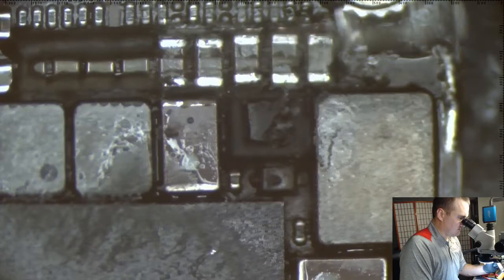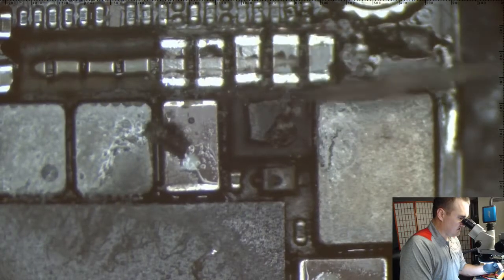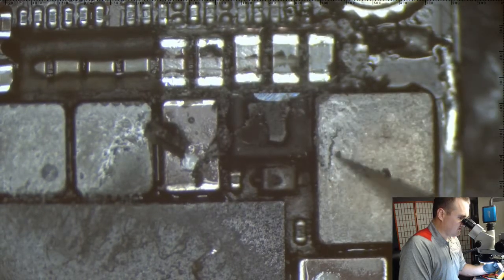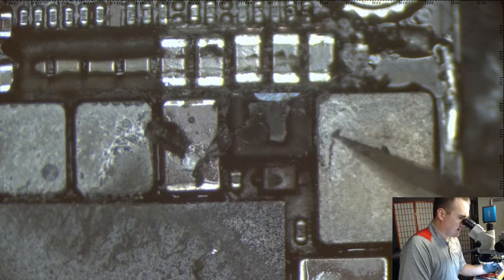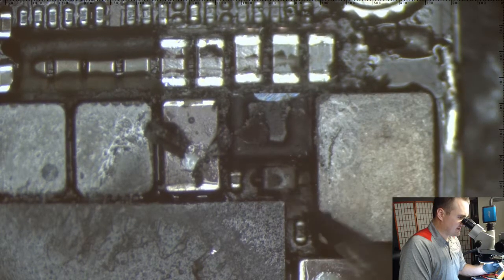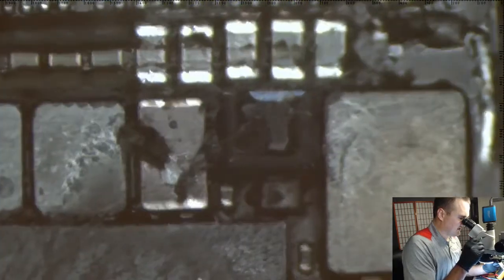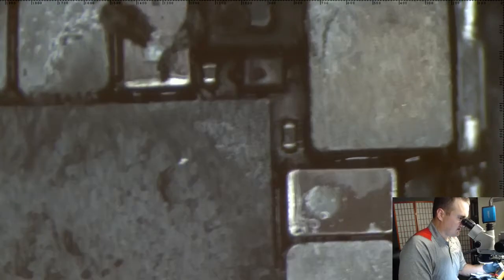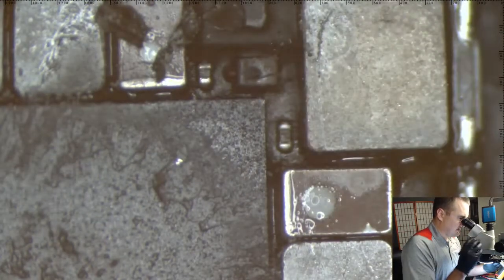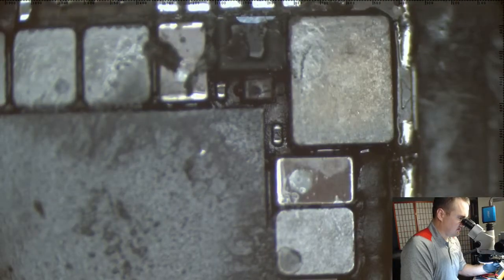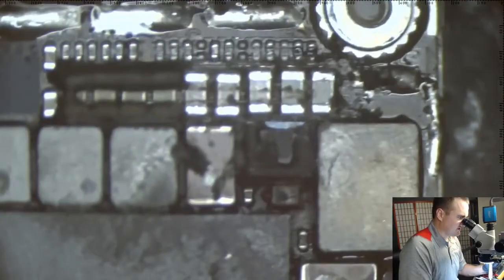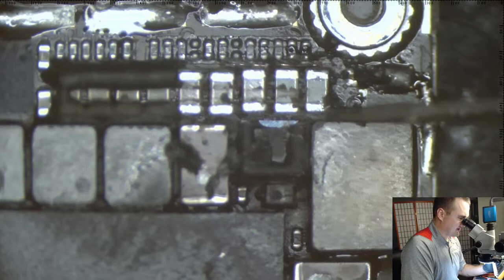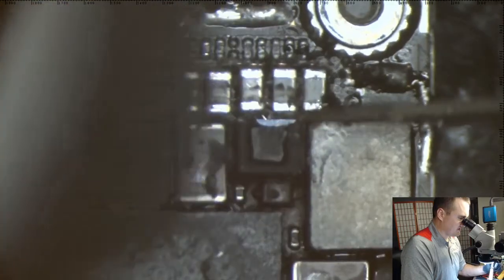Alright, so what happened? Why did this backlight fail? As evidenced by the burnt coil that we just scraped that little poop off of, and you can still see the crack in it. The burnt diode, there's not supposed to be a dot. You can't get any closer than that, that's about as far as the scope's going to zoom. But that's a burn mark. That's a totally burnt out diode. That's because your 19 to 22 volts of backlight power, instead of going to the backlight, went straight back into ground. We have a short to ground situation here.